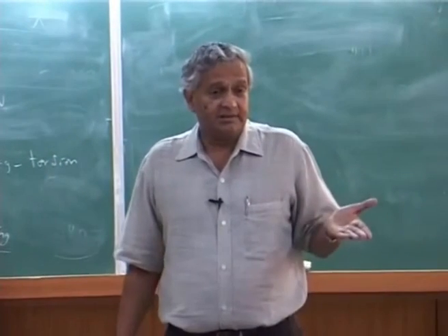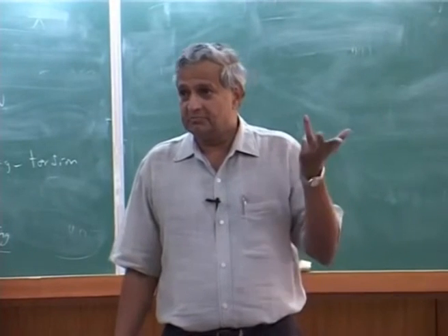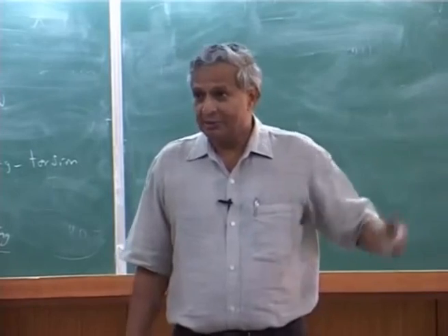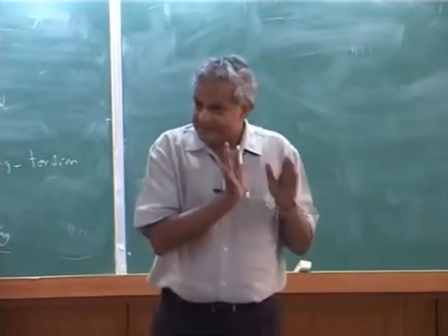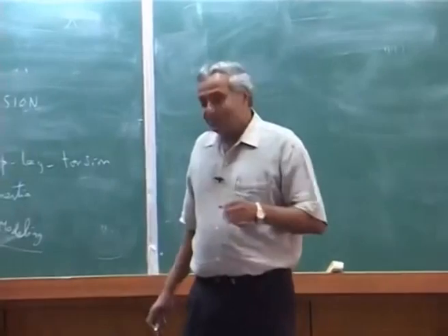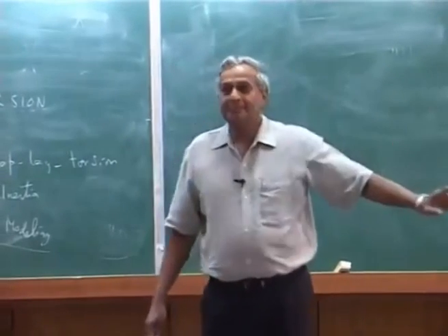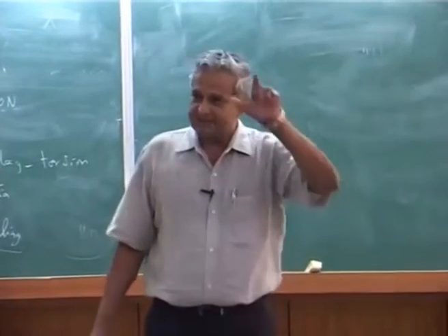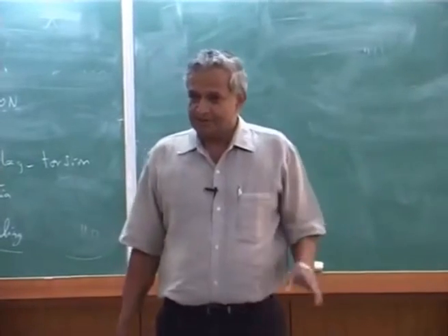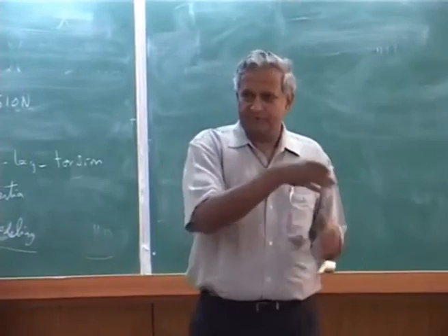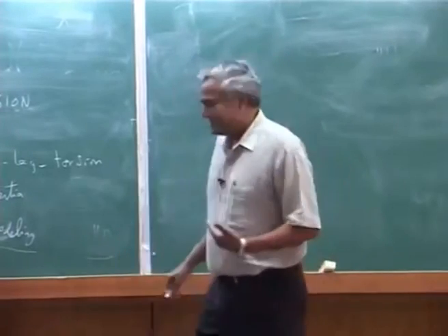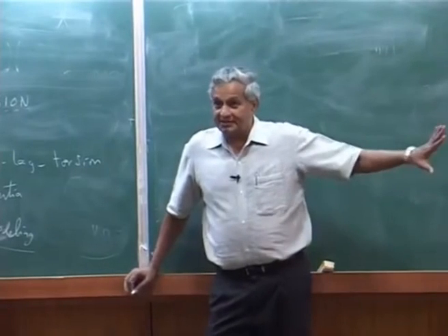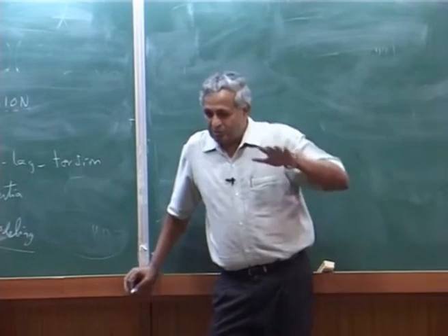Now is the inflow constant? It can vary with time. Then how do you model that? Inflow modeling itself has gone through a very interesting development. Today we have certain models which were developed, like dynamic inflow, dynamic wake, etc. These are all global theories.